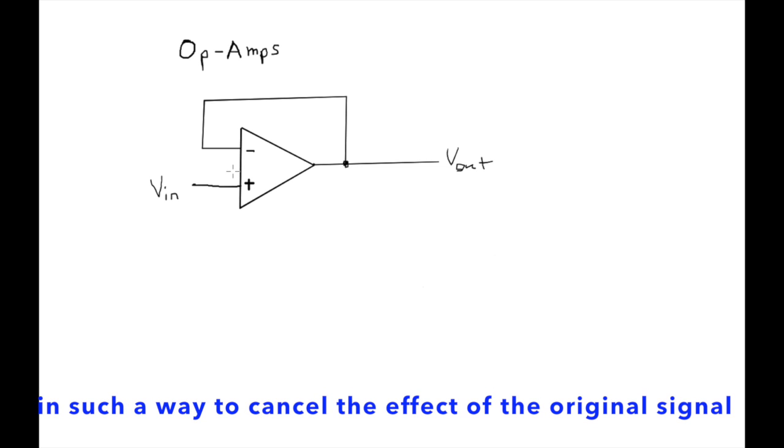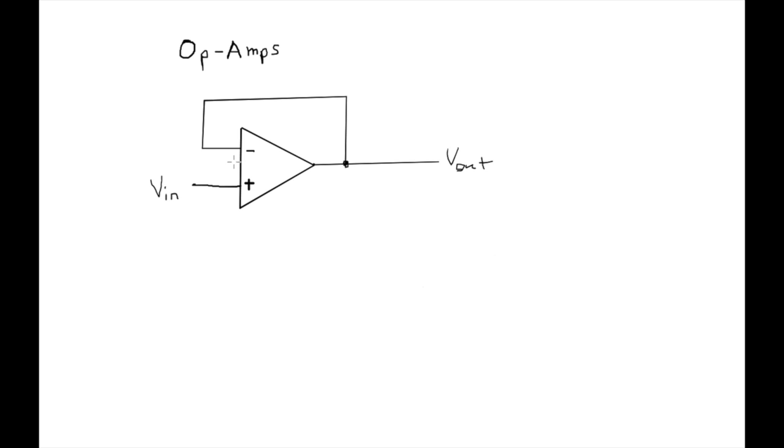Okay, first of all, I want to investigate the following circuit. So I have an input like this, in, and here is my output. So what happens in this circuit? First of all, I know that there is negative feedback here, because when the input is positive, then the output will be negative, and it's going to feed this back to the input of the operational amplifier. And I can use the rules for the closed loop operation in an op-amp.